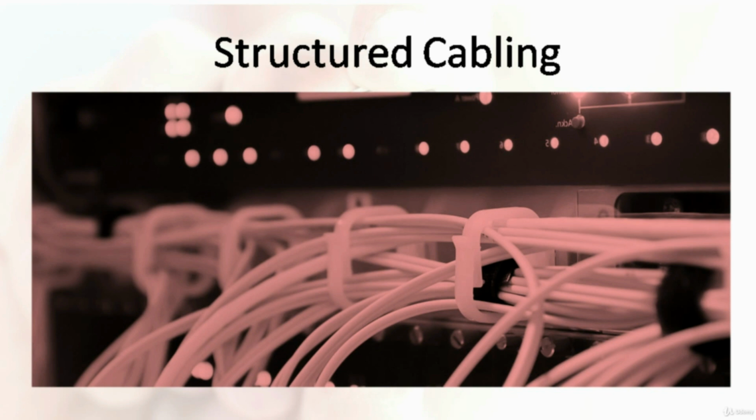Now, most of the cables of your facility will be residing indoors, but there will be cables residing outdoors as well, such as from the telecommunication demarcation point, which is usually off a pedestal, to your building. These cables will need further requirements as they need to be outdoor rated as well. On top of the requirements of indoor cables, you will also need the cable to be water resistant, and in the case where the cable will be exposed to sunlight, it needs to be UV resistant as well.